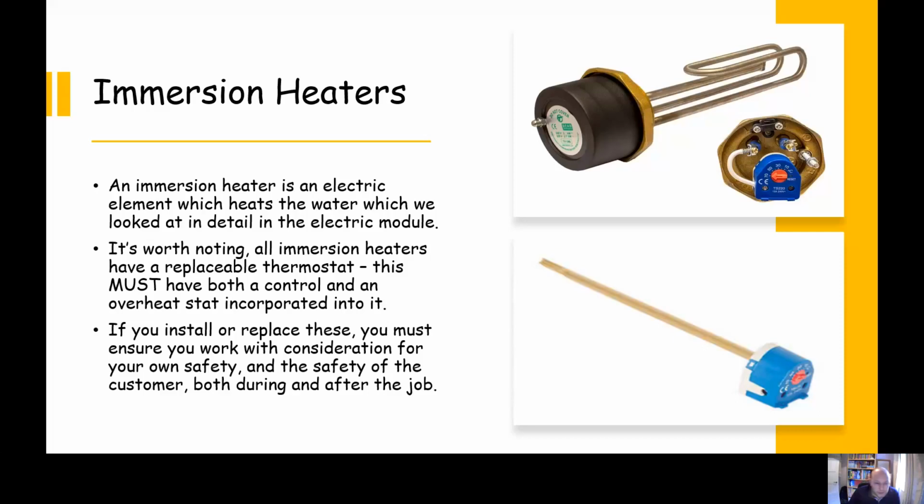It's worth noting, always make sure if you do install or replace an immersion heater or even an immersion heater thermostat, that you consider your own safety. You carry out safe isolation procedure and carry out all the correct procedures to make sure it's safe. Check the overall installation as well. Check the quality of the wiring to it, and if it needs replaced, replace the wiring as well. Essentially make sure that you're safe as you carry out the job, and also your customers are going to remain safe after the job's been completed.